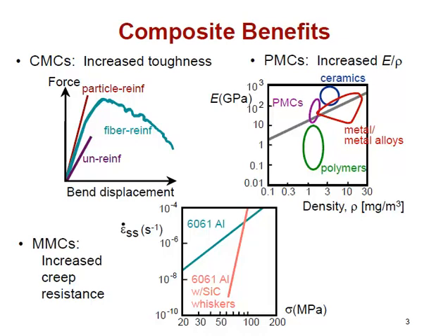In the case of a fiber reinforcer of a ceramic matrix composite, we see a little bit different behavior. That's the sort of aqua blue line in between the two other curves. In that case, we initially get a higher modulus than we would the unreinforced ceramic, but at some point that modulus heals over just a little bit. We get a flattening of that slope, even though it's still a straight line.